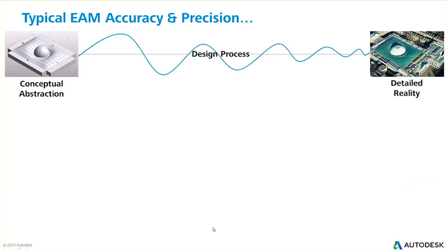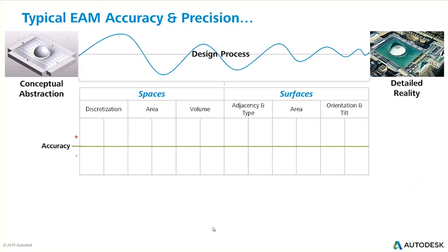Just a note, again, I get asked a lot about the accuracy of the energy analytical model. The thing to remember is that with energy analysis and simulation, the key thing is about comparison and not necessarily about exact quantification. Throughout the design process, it's a bit of a moving target anyway. You're going from a concept to a detail stage, and ultimately an analytical model is an abstraction, but you're trying to represent reality. But we've developed a method for computing the accuracy from a geometric perspective.